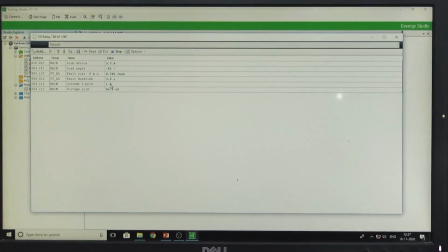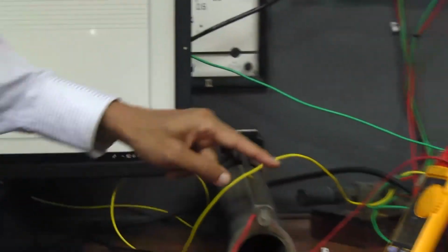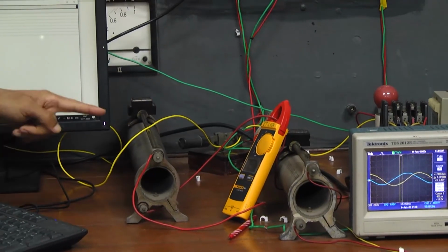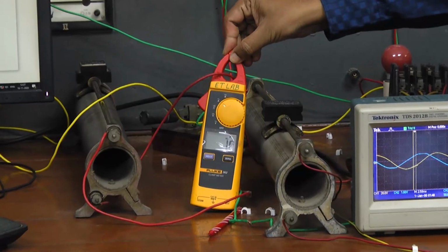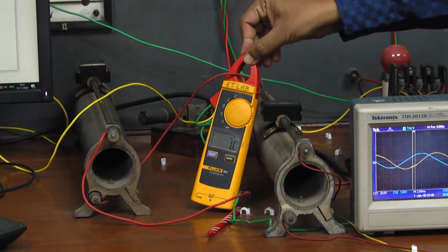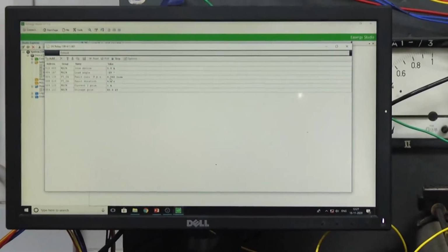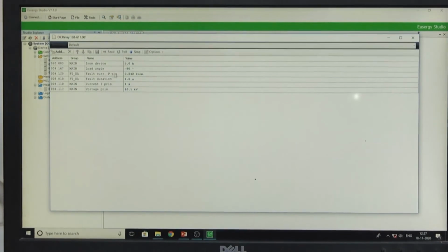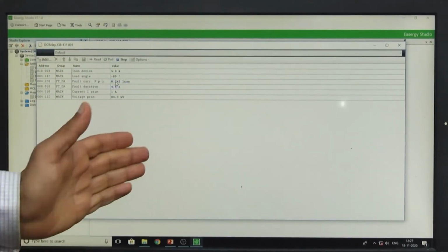So, that reveals that our current and the voltage angle, which are the essential part of the decision process, are in agreement with the circuit from the relay perspective. To have the trip operation, we will go for the current increment first. If the current exceeds the pickup, then the relay is expected to trip if the corresponding angle is within the beta and gamma limits.